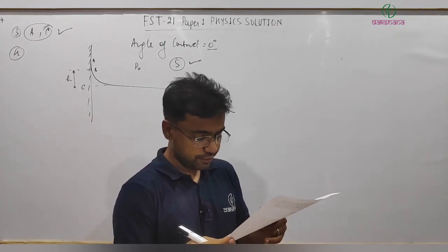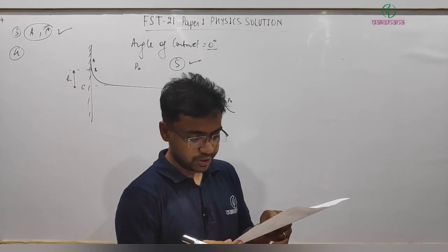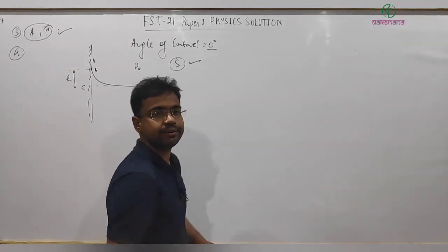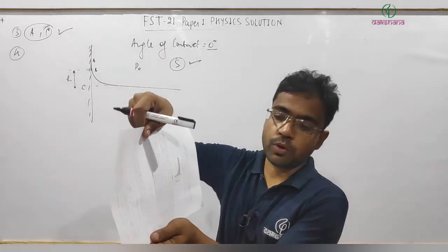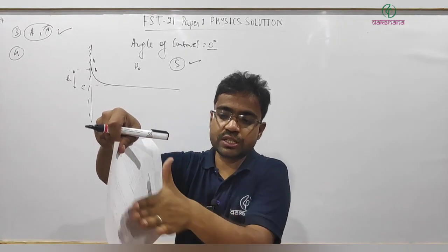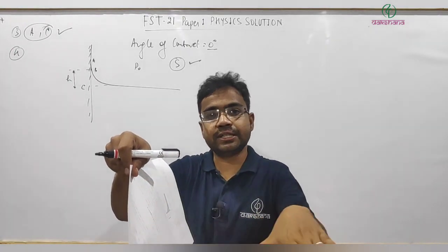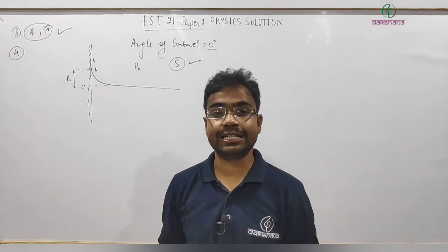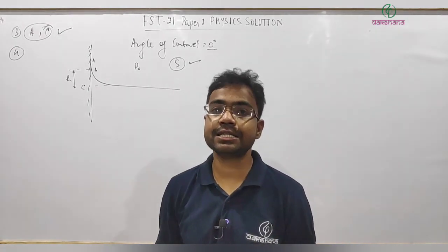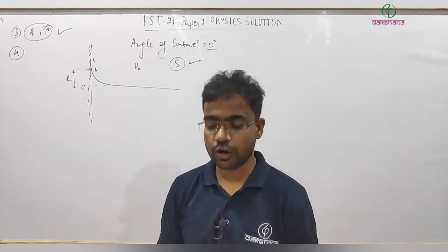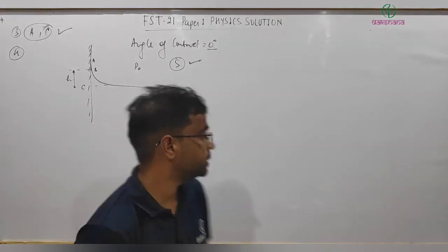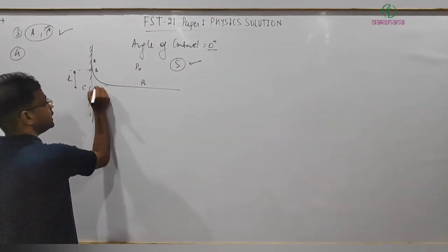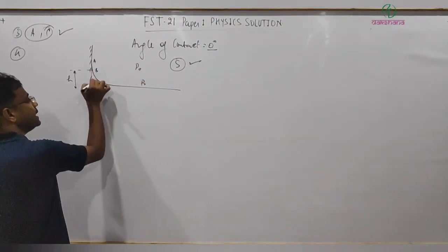Now the radius of curvature of the meniscus at the point of contact; this we can write. First, this is a wall and the surface is like this, so it is like a part of a cylinder, and we must know the formula for the excess pressure in the case of a cylindrical surface. Here the pressure is P0, and this height is rho gh.